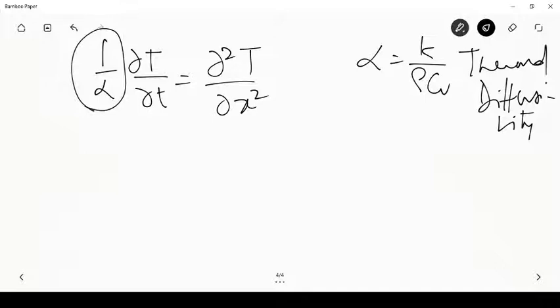Okay. So now if I take this equation and do an order of magnitude analysis. What is an order of magnitude analysis? We are not trying to solve this equation, but trying to look at what each term would be of the order of. How big is each term? And using that, getting an idea. It's not going to be an exact solution, but it will say what it will vary with, what something is proportional to, and so on. So it gives you a physical understanding of the problem, not a quantitative but a qualitative understanding, based on some quantitative estimates or feelings that you would have from the understanding of the physics. So let us try to do that.